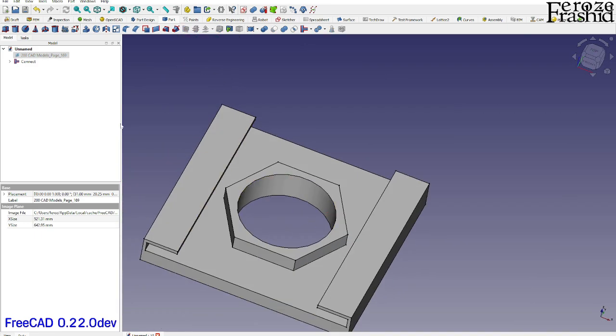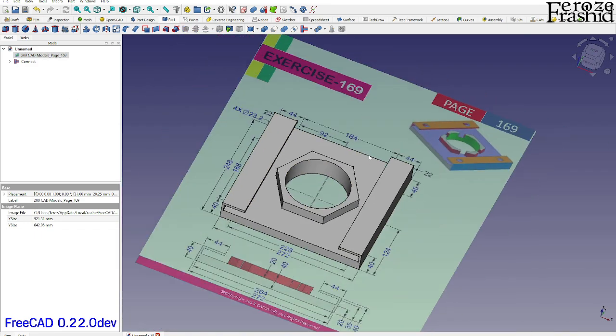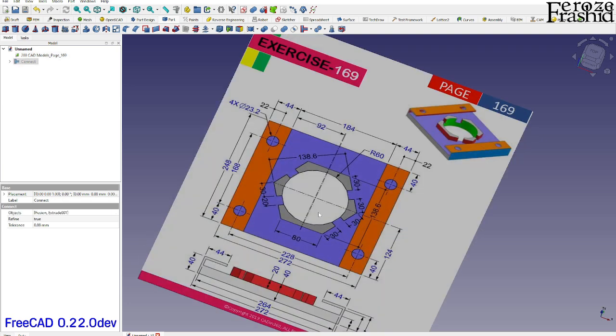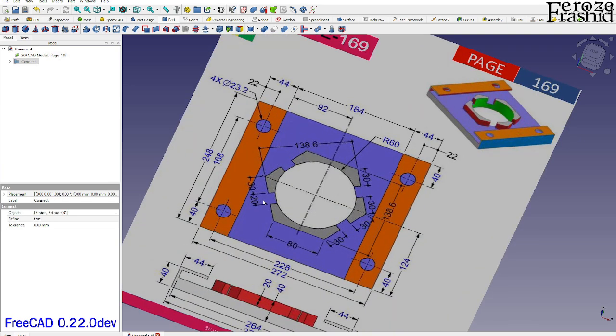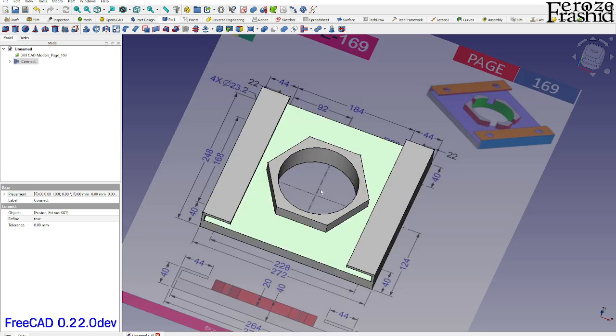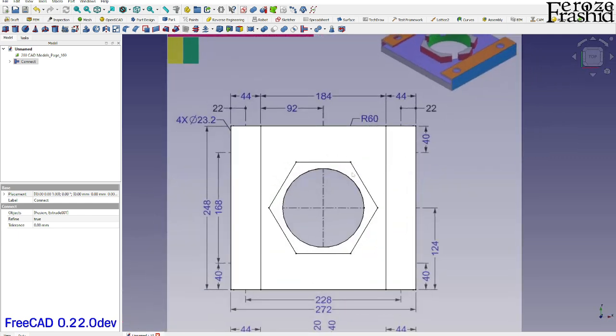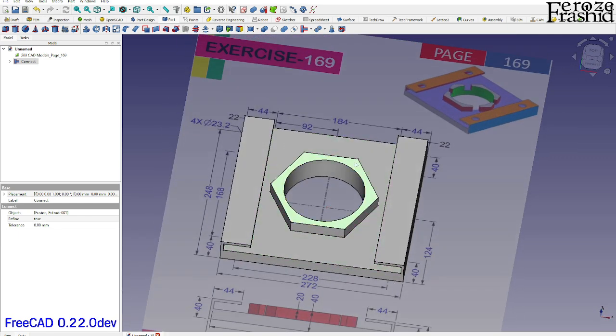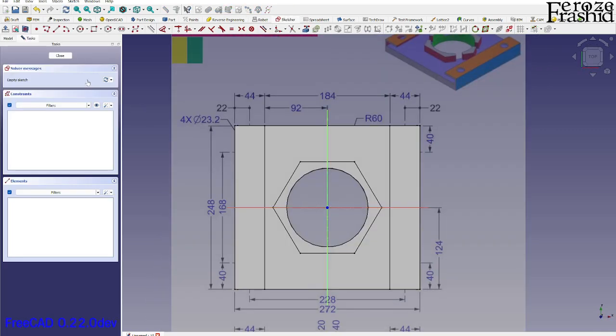And finally I have to make these notches. Okay, so these notches are a 20 millimeter gap and 30 millimeter from one of the sides. Should be simple. I would want to draw it on this face, and I want to say sketch on that face, and here it will be two rectangles. Actually, I don't think it will be, something like this.